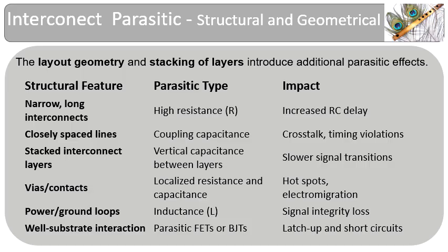Closely spaced nets: dense routing increases the adjacent nets' coupling capacitance and impacts crosstalk noise, glitches, dynamic power dissipation and false switching, etc. Stacked interconnect layers: in order to optimize die area, the interconnects are routed in multiple vertical layers. The stacked layers create interlayer capacitance that also adds to the load capacitance. The cross-layer coupling leads to signal integrity issues and dynamic power consumption.